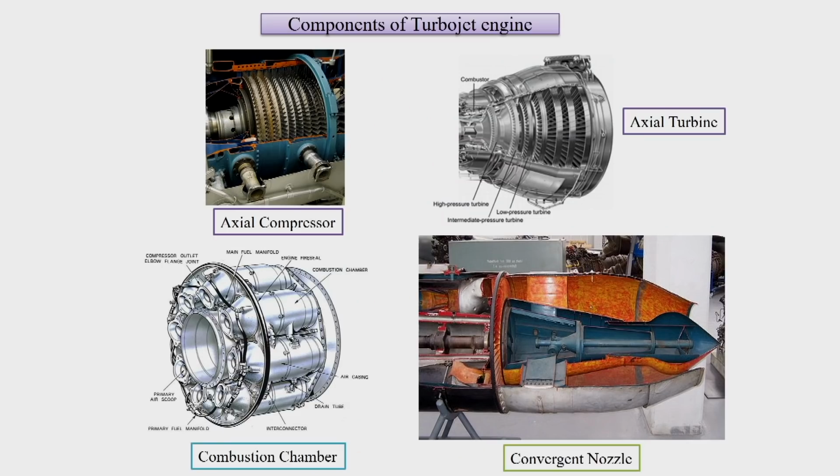As we said earlier, the turbojet engine is an aircraft engine which is turbo based. We don't need W net there. Our requirement is that we want the enthalpy to remain at the nozzle inlet, such that upon the enthalpy decrement, that energy can be converted into kinetic energy, and that kinetic energy will be used for propulsion.